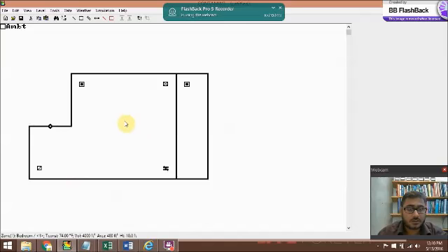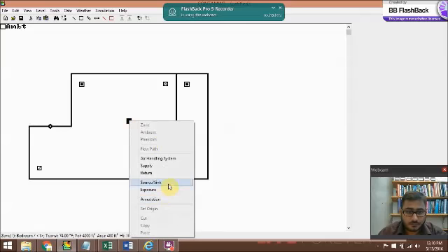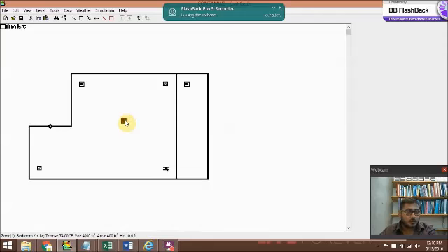Next we would model sources and sinks to determine different materials. Can you, okay, so you did the air handling unit itself, a supply duct and a return duct. In most bedrooms, for example, you would not have a return duct. You just have the supply duct. If you did not include the return duct, would that work, or do you need a return duct somewhere? It would work. In case there's no return duct, the only place the air could go out is the leakages or the windows.